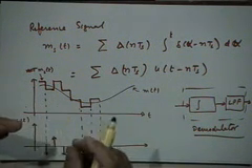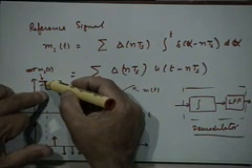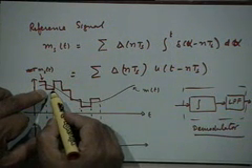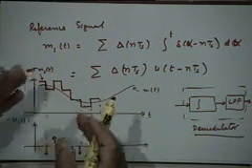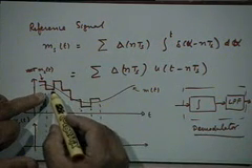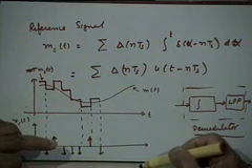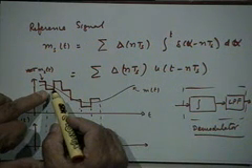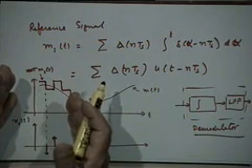But this loss of information may be insignificant if, for example, your step size is very small and your sampling interval is also very small. But in practice, you cannot make both these things indefinitely small, because if you do that, what will happen? If your step size is too small, you will see there are some disadvantages. But if your pulse interval sampling rate is too large, right? You are obviously having to transmit information at a very large rate. Your rate of information transmission will become very large, right? Is that clear? So we don't want that also, because that is in a way going to use more bandwidth, right? So there are those pros and cons.